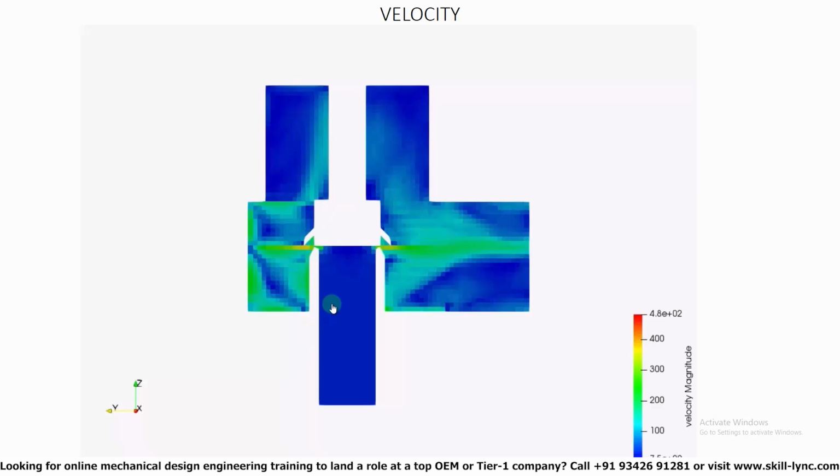Now, for those of you who have seen pressure cookers, you know that the pressure actually builds, and once the built up pressure is higher than the pressure it takes to lift the valve, you will basically have pressure relief, right? But in this particular case, we don't have a completely closed seal between the pressure line and the rest of the pressure valve, and this is a fundamental flaw in our computational model. So then the obvious question is, how are we going to fix it?